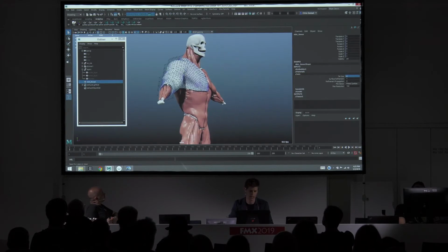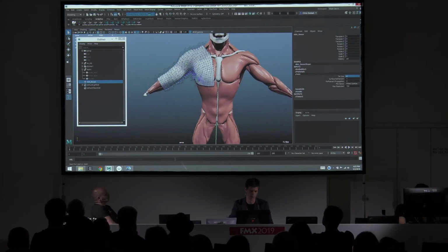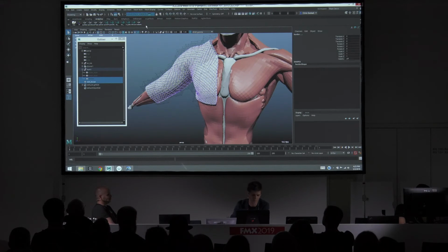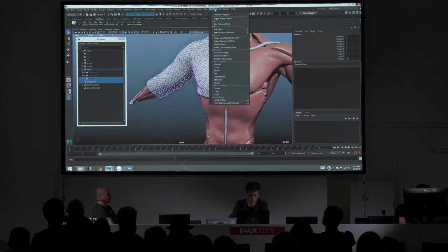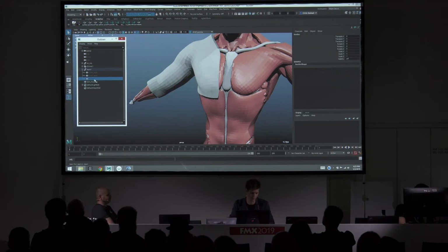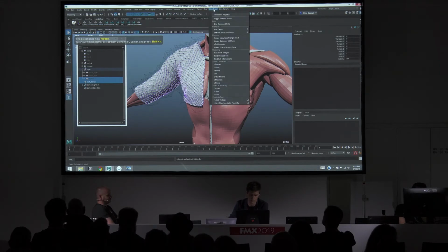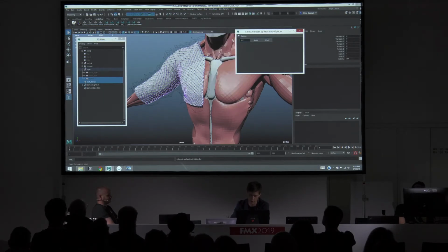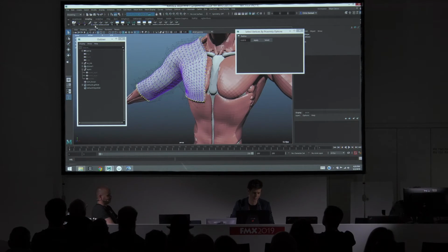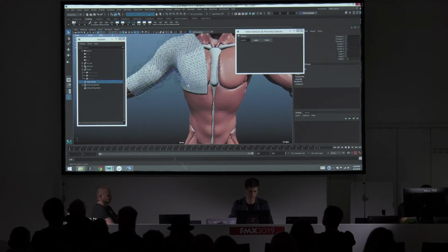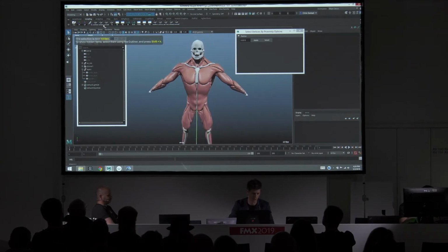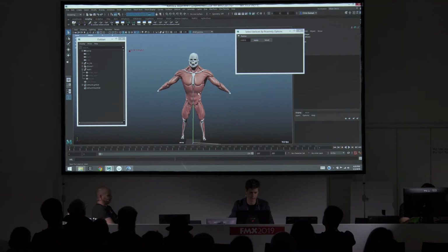And then I'm going to attach the ends. I'm going to attach all the borders to the underlying bones. And to do that, I'm going to use one of my scripts, because I don't want to manually make all the attachments, because that'd be boring. So I can do a vertex selection. I can use our proximity tool to do the vertex selection. I need the tissue first. Then I'm going to use all the vertices that are adjacent to or concurrent to the border. Ziva tools, select vertices. I'll make this really low because they're on top of each other. I'm going to store that selection. And then basically I'm going to use something that's going to allow me to look up the closest point on everything and make the attachments that way.